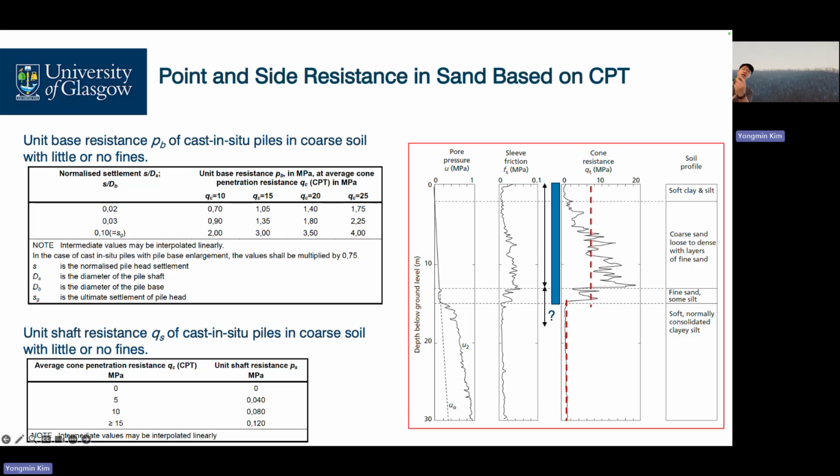This is the way you design your pile length. Not enough. Not enough. Here is the field. Residual soil. Only 1 meter of weathered rock. But if your Lp is not enough, you increase the length. Socket it more and more. It means your end bearing significantly jumps up, and your shaft resistance in the rock also increases.